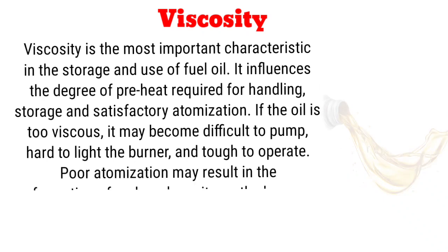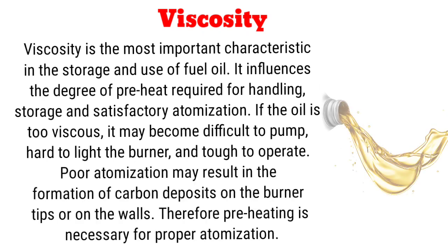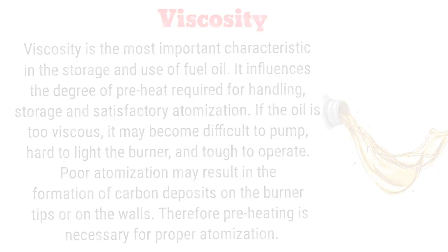Viscosity is the most important characteristic in the storage and use of fuel oil. It influences the degree of preheat required for handling, storage and satisfactory atomization. If the oil is too viscous, it may become difficult to pump, hard to light the burner, and tough to operate. Poor atomization may result in the formation of carbon deposits on the burner tips or on the walls. Therefore, preheating is necessary for proper atomization.